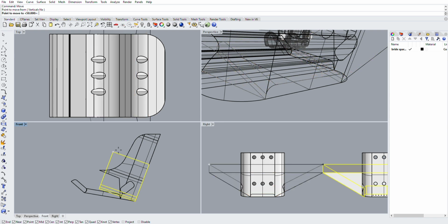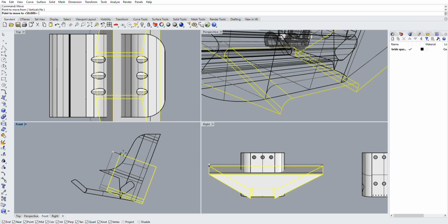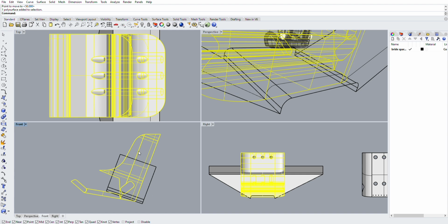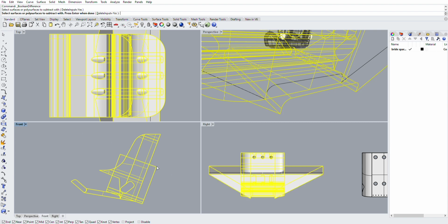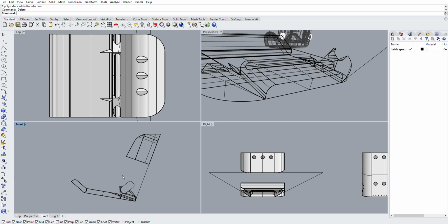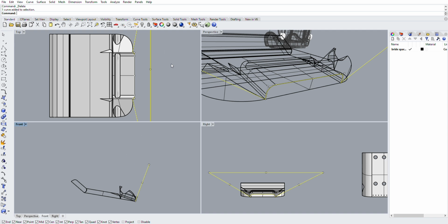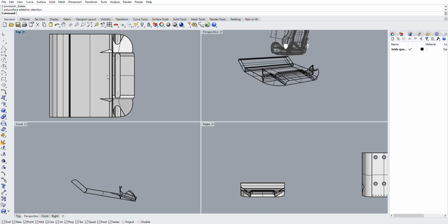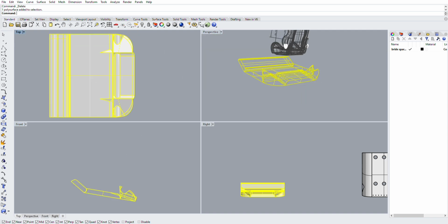And we're back to the solid difference tool. All I'm doing is dragging it through here. It usually removes, but I found that every once in a while it gives a file where if I haven't dragged it past the edge of the solid, it does a weird thing. So it's a habit that I tend to remove it. But once the top's cut apart, there's nothing holding it to the bottom, and I can actually just remove it. And now with it like this, I can actually explode it.